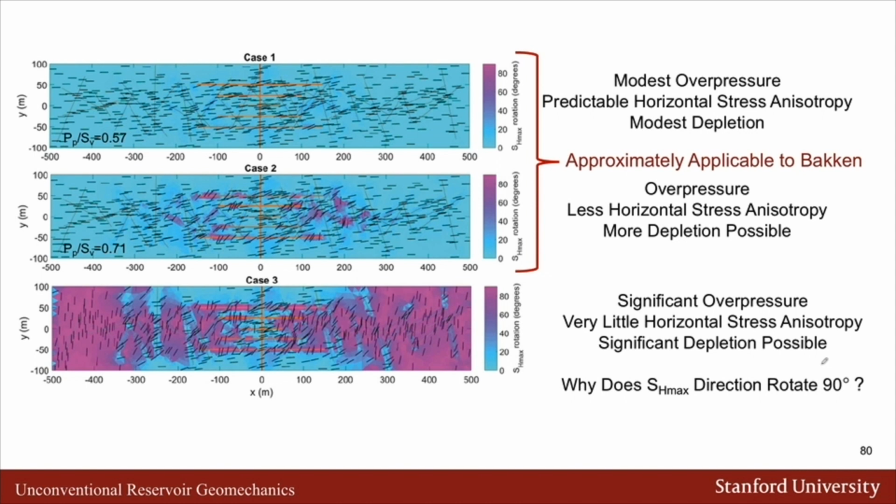So again, as you approach the depleted zone, say, in the vicinity of well H1 with either H2 or H4, the hydraulic fractures are propagating with the direction that one would have expected from the regional stress field. But actually, in the vicinity of H1, if the fractures actually got that far, they would be propagating with some new orientations.